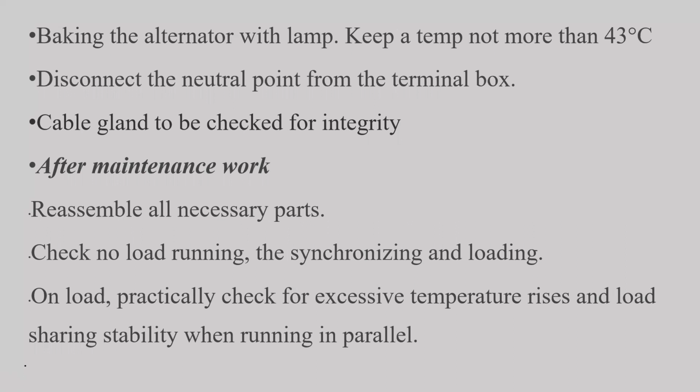After the maintenance, what has to be done? Reassemble. Whatever portion was dismantled has to be reassembled, all necessary parts. Check the no load condition. First, we have to run the generator with no load testing. Then step by step, we can add some loads and synchronize it. On load, practically check for excessive temperature rise, rated current, rated voltage, and we have to check for stability when it is running in parallel condition. So these points are taken care of after the maintenance work.